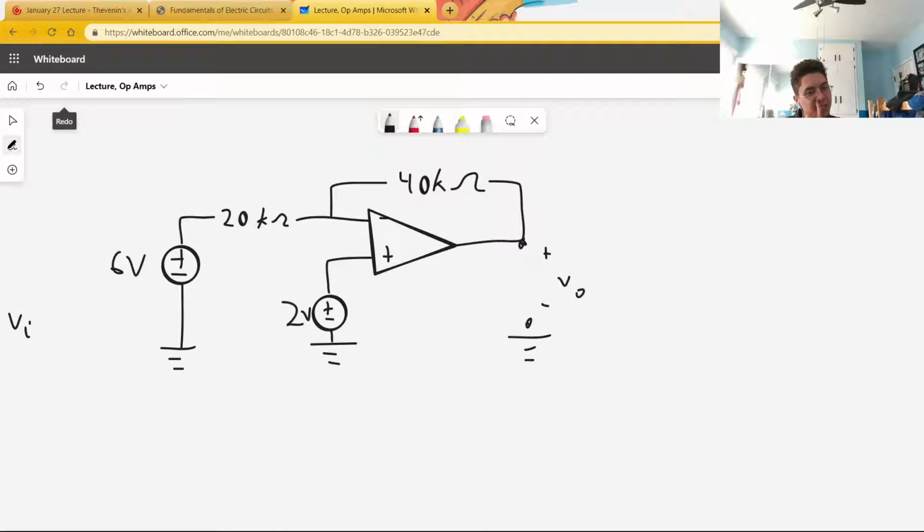We will now analyze a circuit similar to an inverting amplifier with a slight hiccup, this 2-volt battery. First, consider the fundamental assumption of voltage. What is the voltage at this point? It is 2 volts. Which means, and so we're going to scaffold our knowledge, this must be a 4-volt drop. Therefore, by V over R, there must be 0.2 milliamps going through this resistor.